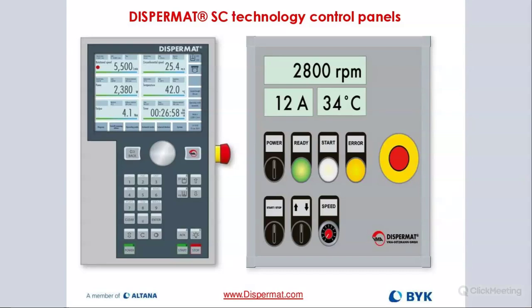So some people say, okay, I don't want to turn the machine off. I just want it to run with 20 or 30 RPM. So at least it's mixing while the material cools down. So that's one way of protecting the material from overheating, these cutoff values. I can also run this machine, if it has the C technology, with constant power. That means in this case, you can see that red dot right next to the 5,500 RPM. That means I locked in 5,500 RPM.